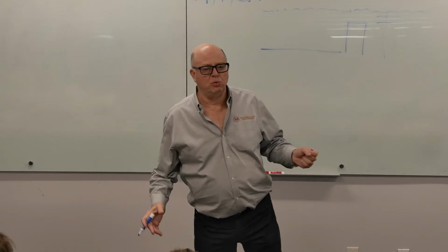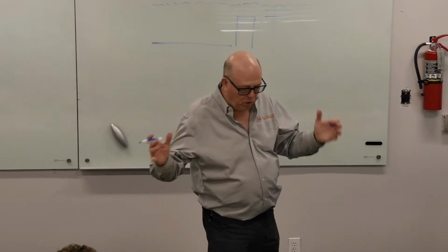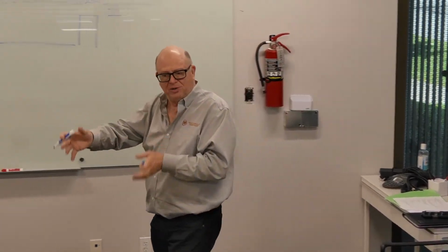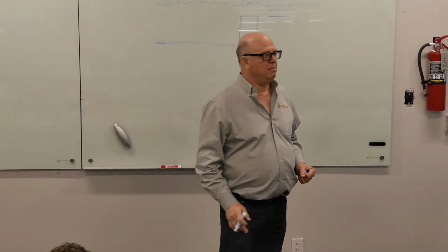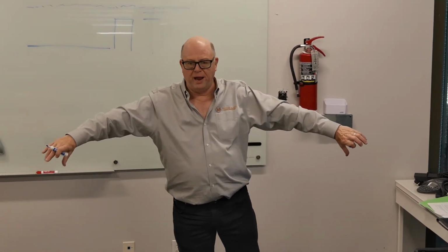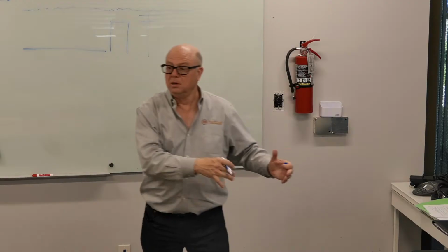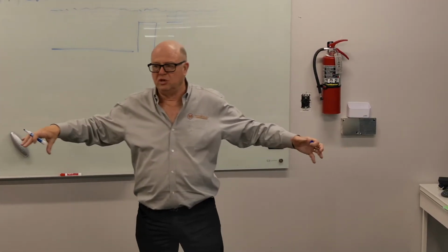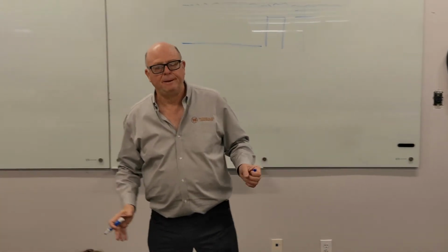So here we have a suite. It's got 4 operating rooms and a sterilization room, which has to be at negative pressure, right? You have to keep the ORs at positive pressure, and various other things. There's also the sterile corridor that goes by outside the ORs and the sterilization room and the storage room where they keep all the surgery supplies. And there's a bunch of specific things that you have in every one of these surgery centers.